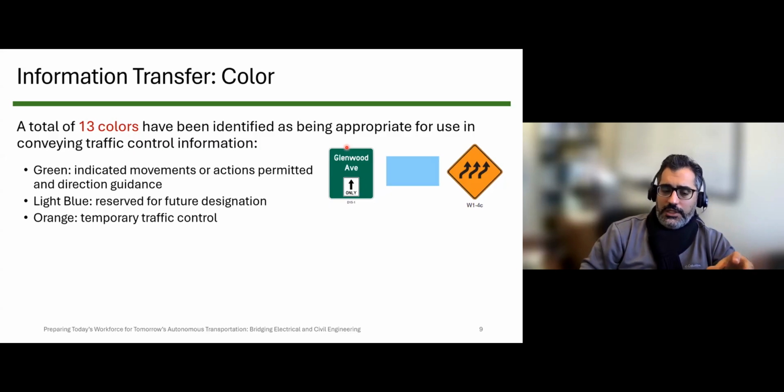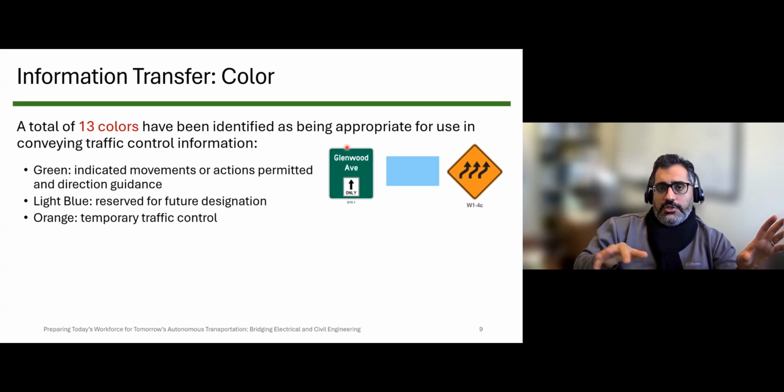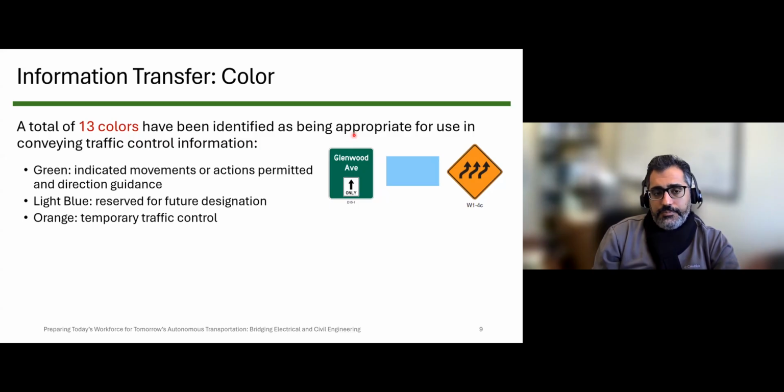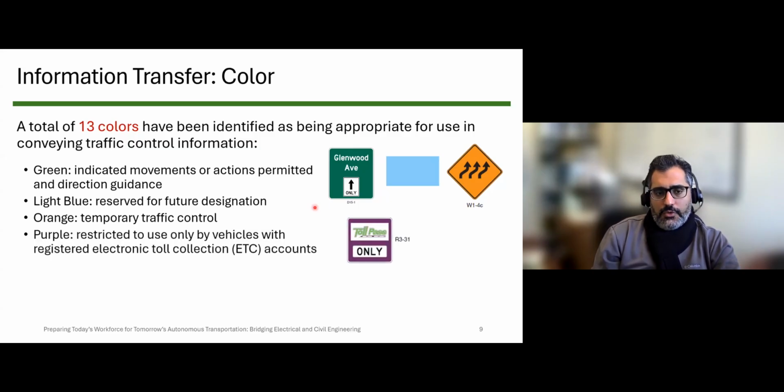If we have construction, like imagine for construction purposes one lane of a 4-lane highway is completely closed, so we need to diverge the traffic, these 3 lanes, and how we do that is we apply longitudinal markings, solid marking. I'll talk more about that in a few minutes. But we will also apply these signs that will use orange background.